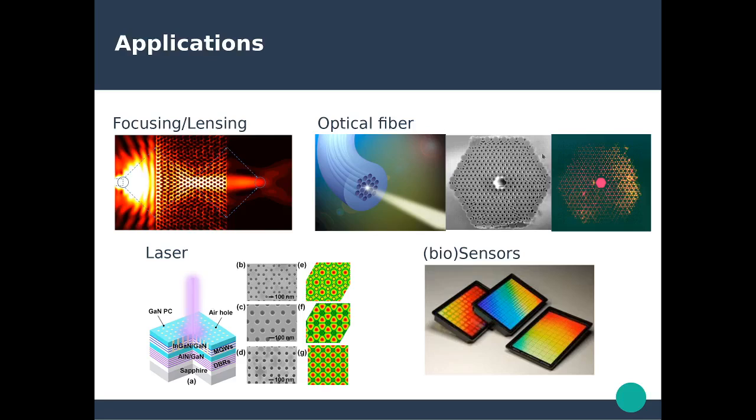Optical fibers have benefited from photonic crystals. So rather than having a very bulky glass optical fiber, you can design a very small photonic crystal type of fiber that will confine the light within this line defect. This is a defect line that runs through the fiber, so light is being confined and does not penetrate within the crystal when the optical field propagating here has a frequency which lies in the band gap of the photonic crystal.